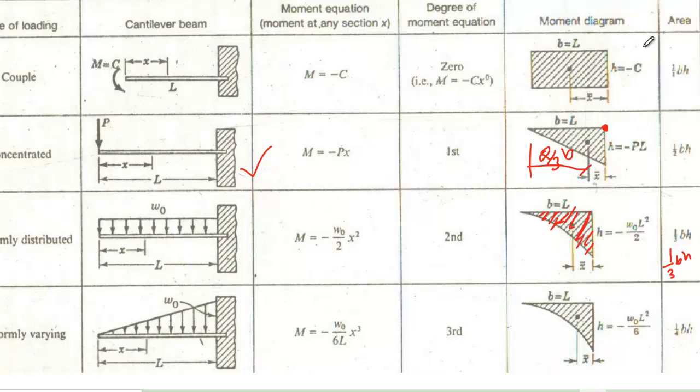So now this shortcut you can also use for your complex moment diagram technique, SFD BMD technique. That will give you an approximate result, not accurate, but it will help you find the result faster than the complex technique. So 1/3 of BH, and that would be 1/4 of B.